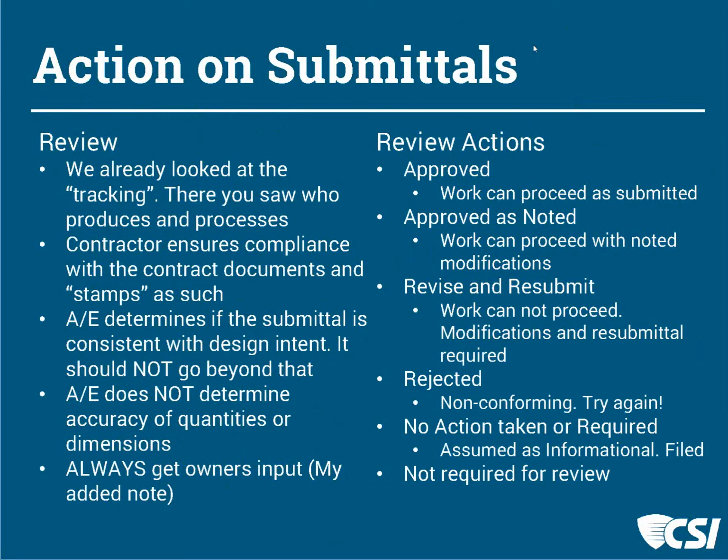So we've looked at tracking. We've talked a little bit about schedule and who produces it and processes it to us. The contractor should always receive this prepared submittal first and take action on it. So the contractor reviews the documents for compliance and then stamps that package before you receive it.